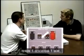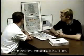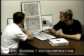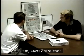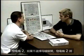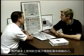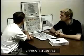The generator 1 disconnects itself from the AC bus 1, and it allows the number 1 pump in the left and right wing tanks to be powered from the generator. Well, assuming that generator 1 is now only powering the fuel pumps in the left and right, what will generator 2 do? Generator 2, without selecting the bus tie off, is going to power AC bus 1 and 2. And what are we setting ourselves up for? We're basically isolating ourselves with the avionics smoke configuration. We're going to isolate the system here.